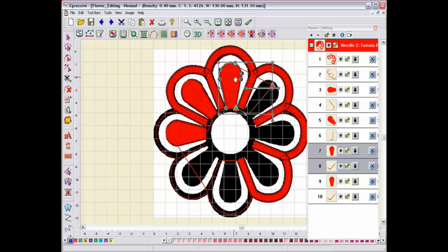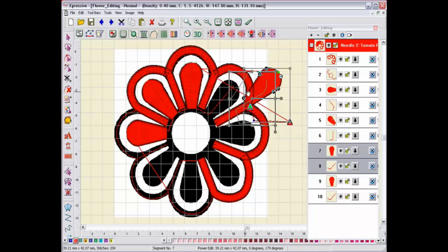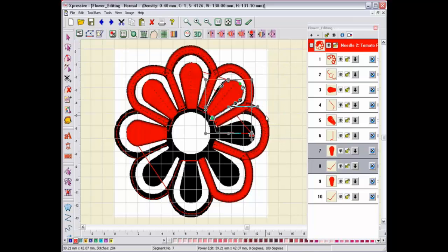new items pasted in will automatically be in Power Edit mode. If you're going to move copied and pasted items, remember to wait until the mouse cursor turns into a hand cursor before dragging these selected segments into a new position. When using the Copy and Paste option, also remember to check your Stitch Sequence Viewer to see if the pasted items have been placed in the correct sewing order.